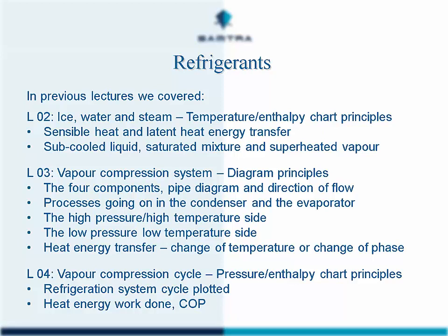And then in lecture 4, the vapor compression cycle, here we actually took the cycle and plotted it on a pressure enthalpy chart. And from this pressure enthalpy chart, we can see the different heat energy transfers taking place in the actual cycle.